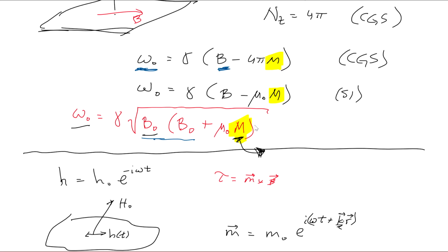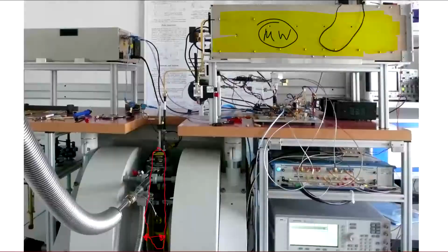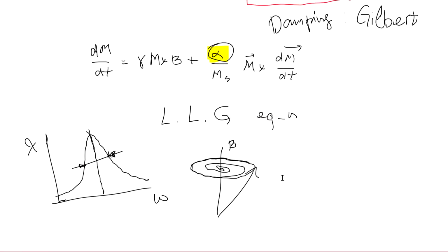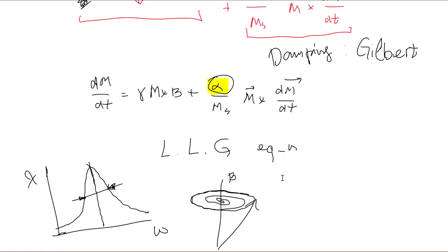So you can judge about the magnetization, but also you can extract parameters like damping, and you can say whether your material is nice and crystalline, how many defects are there, well, not how many, but how defective it is, and basically analyze the material. That is what it is used for in, let's say, magnetics laboratories.